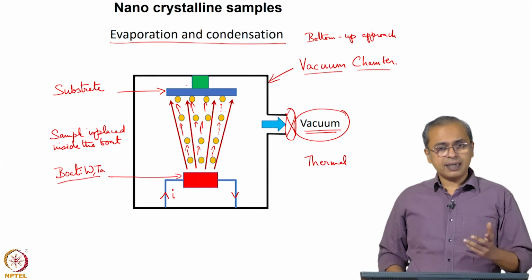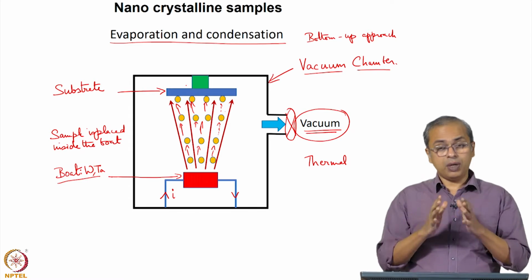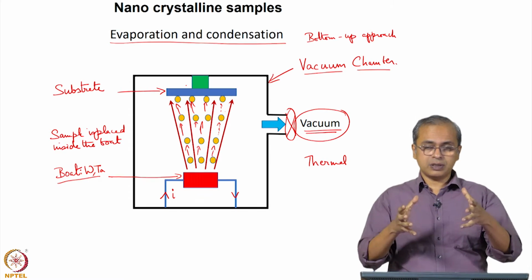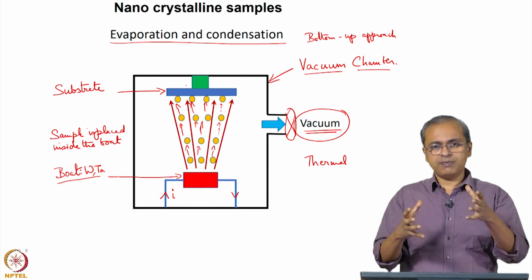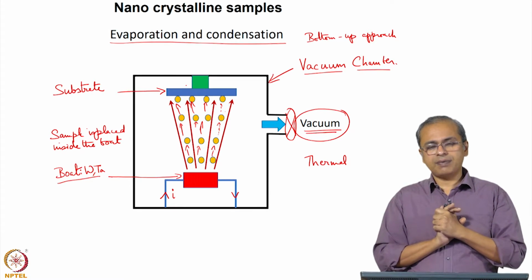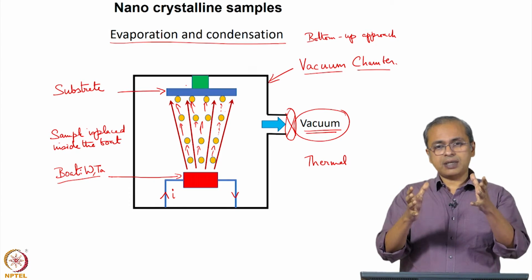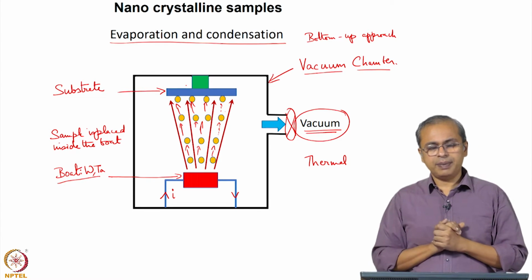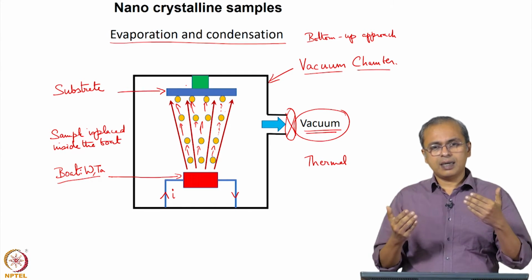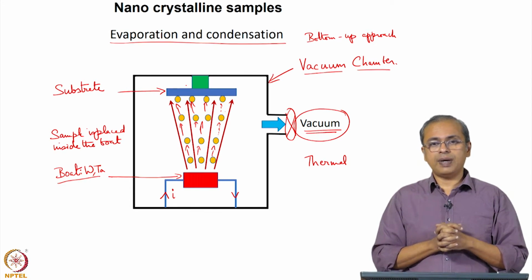Again, if you have the right kind of parts, you can make this in your lab. You have to get the right kind of materials though, because you cannot just take any glass and use it. There will be specific glass materials and jars available which can handle high vacuum, or you can even make a proper vacuum chamber, stainless steel based, with enough wall thickness that it does not get crushed under the 1 atmosphere pressure difference.